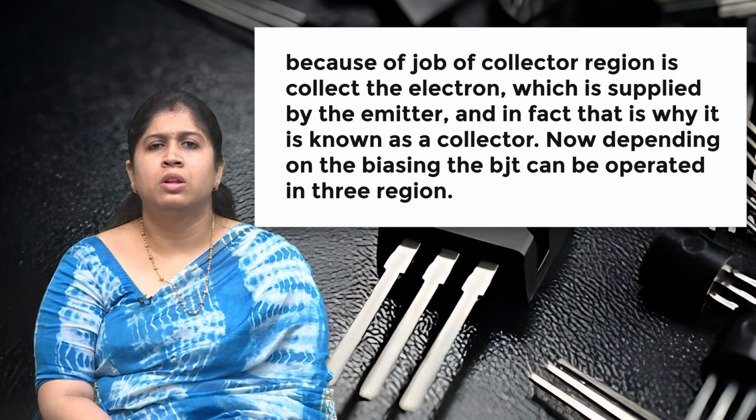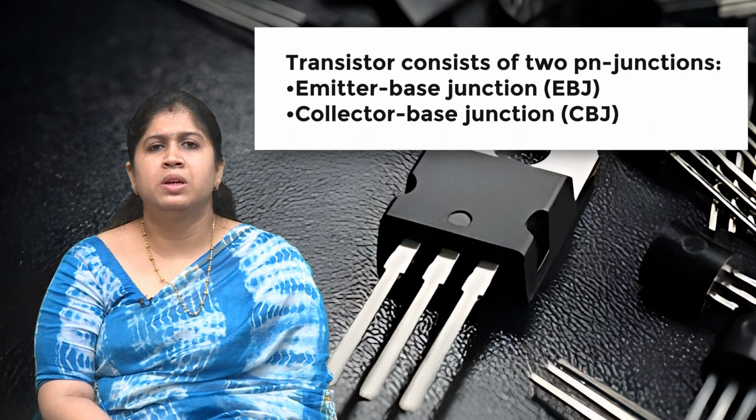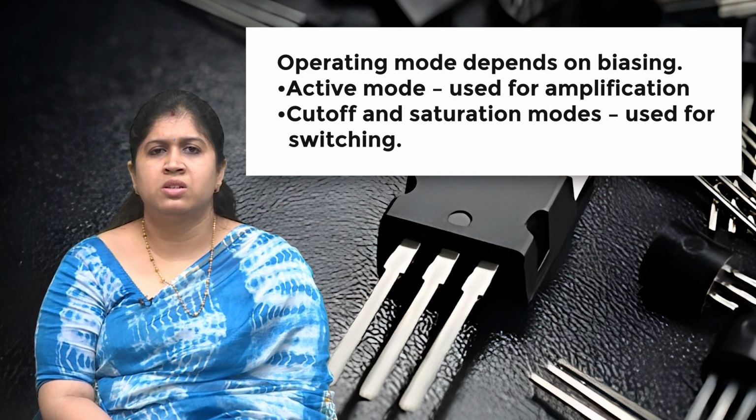Depending on the biasing, the BJT can be operated in three regions. The transistor consists of two PN junctions: the emitter base junction, EBJ, and the collector base junction, CBJ. The operating mode depends on biasing. Active mode is used for amplification, while cutoff and saturation modes are used for switching.